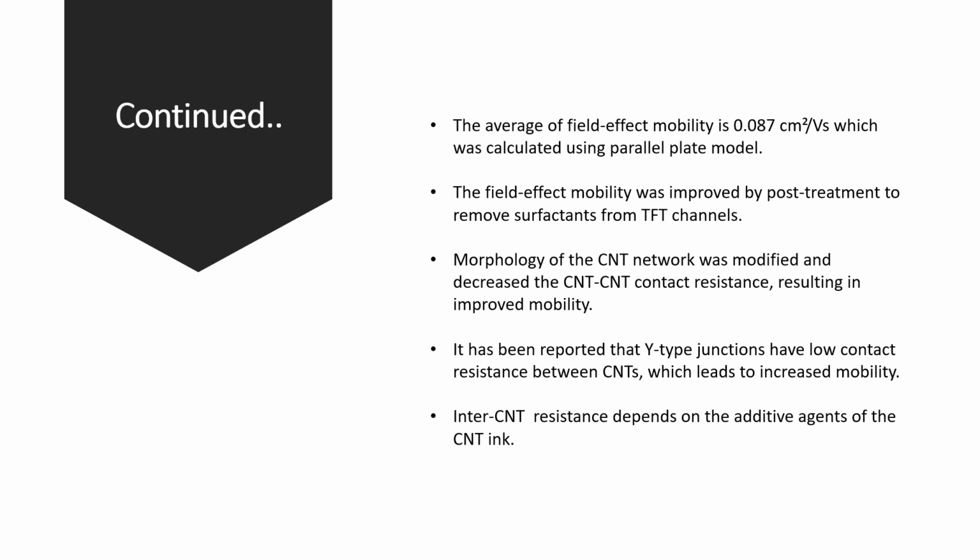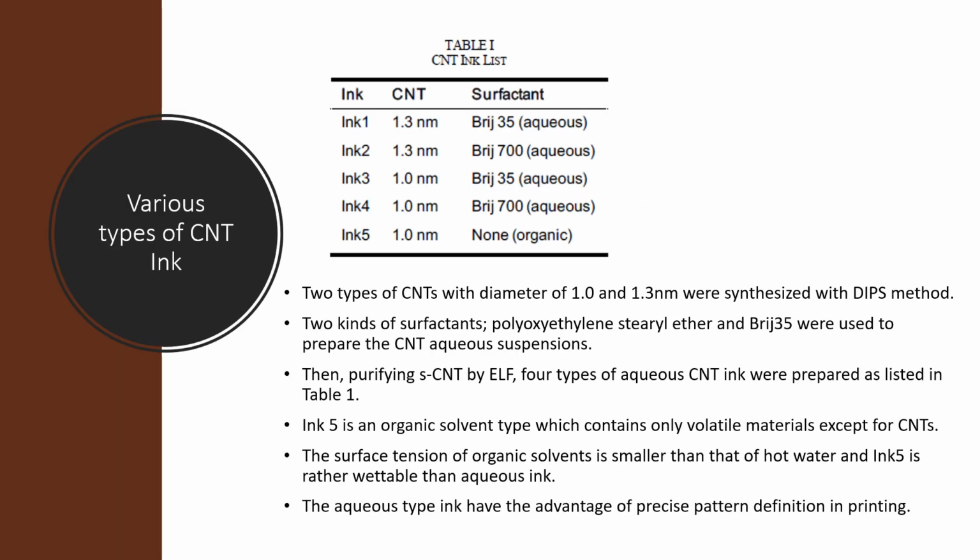The inter-CNT resistance should depend on the additive agents of the CNT ink. Various types of CNT ink were prepared. The semiconducting CNT purification method ELF is available for a variety of CNT diameters and some kinds of polyoxyethylene alkyl ether as surfactants.